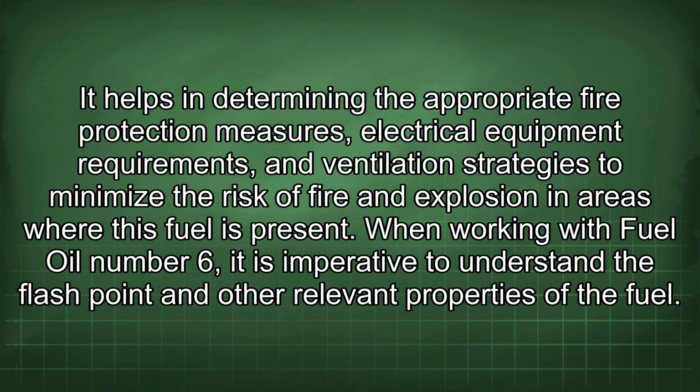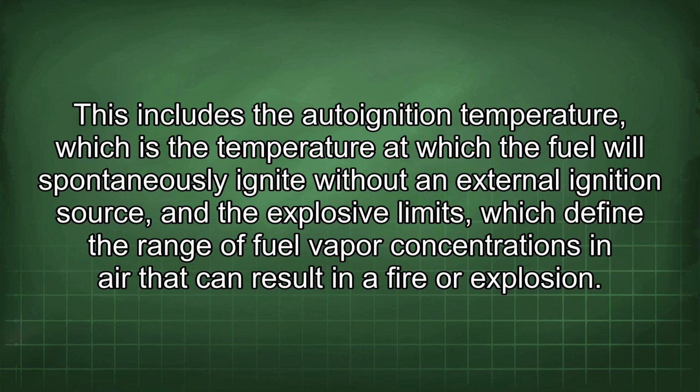When working with fuel oil number 6, it is imperative to understand the flash point and other relevant properties of the fuel. This includes the auto-ignition temperature, which is the temperature at which the fuel will spontaneously ignite without an external ignition source, and the explosive limits, which define the range of fuel vapor concentrations in air that can result in a fire or explosion.